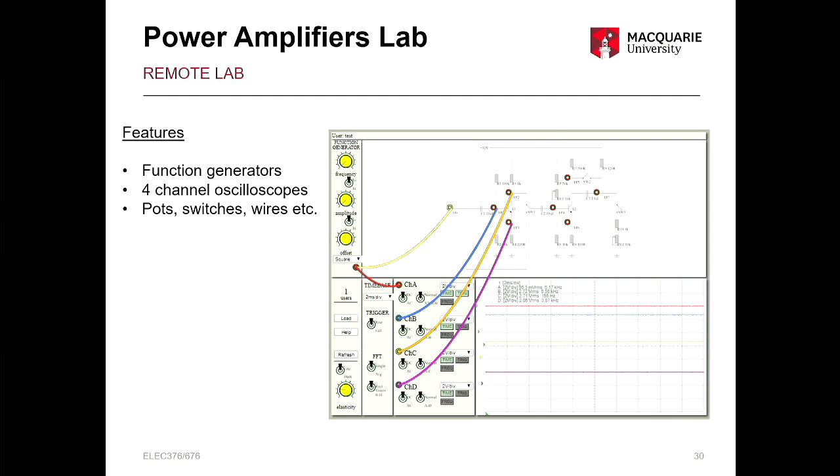And the key one to remember is the potentiometer. There is a sliding arrow like this where you can set up the biasing, and the value of that isn't shown on it. You have to probe it to get the value, under the right conditions. So if you leave it and come back and you want the same biasing, make sure you repeat that step and check the biasing. Don't just log back in and assume everything will be as you left it.